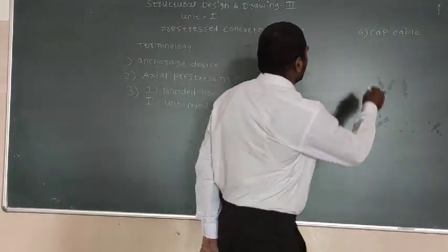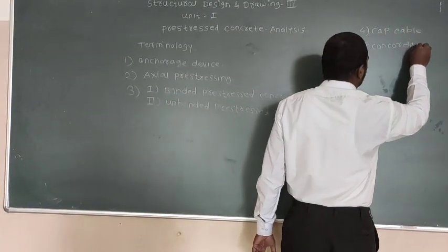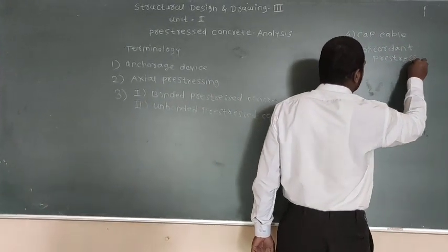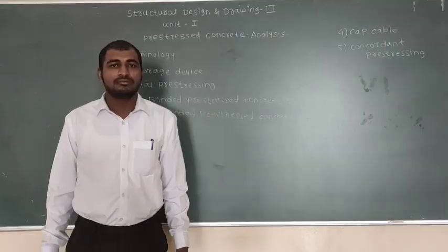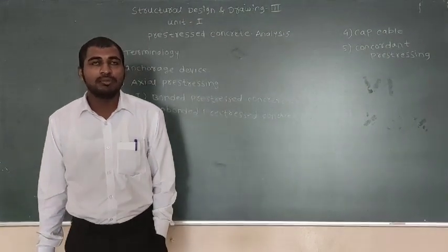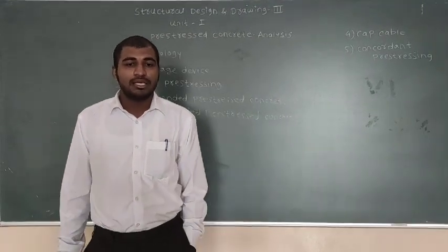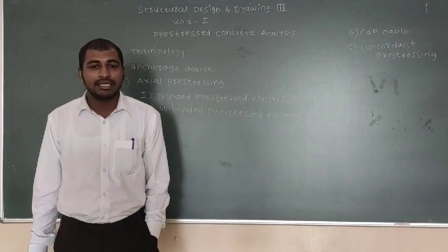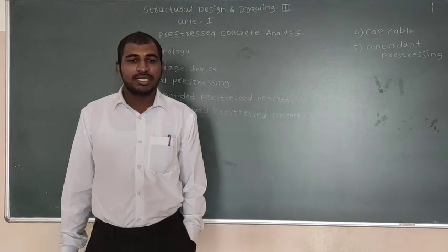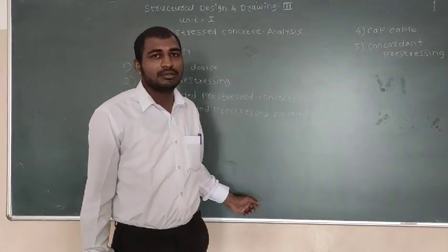Then the fifth terminology is concordant prestressing. Concordant prestressing is prestressing of a member in which the cables follow a concordant profile. In the case of statically indeterminate structures, concordant prestressing does not cause any change in the support reactions.